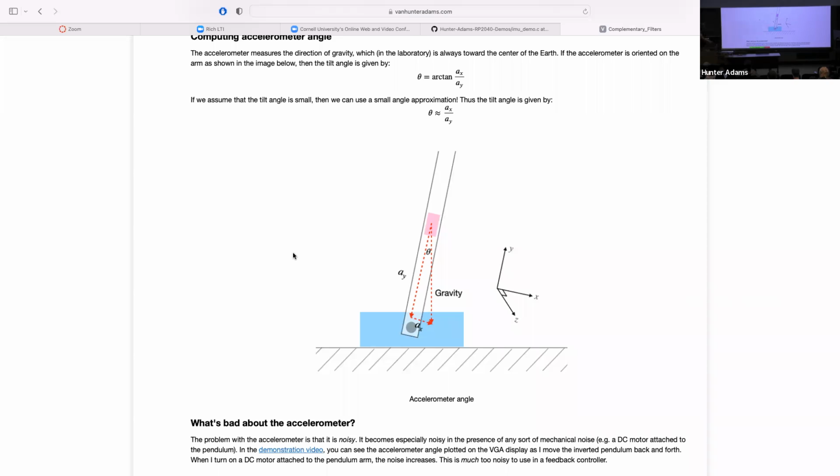What if I ruin the small angle approximation by just tapping it? If you tap it quite far out here, then it's a bad approximation. But you will not be able to recover. If you tap this outside of where the small angle approximation holds, given the speed and the mass of the reaction wheel that we're using, you're not going to be able to catch it. You can only really catch and control these things within a range of angles where the small angle approximation is reasonable. This seems about as effective as just tightening the screw on the pendulum, so it doesn't.